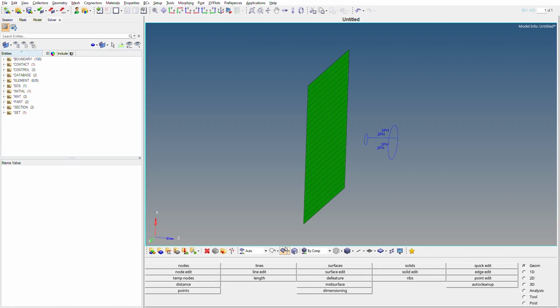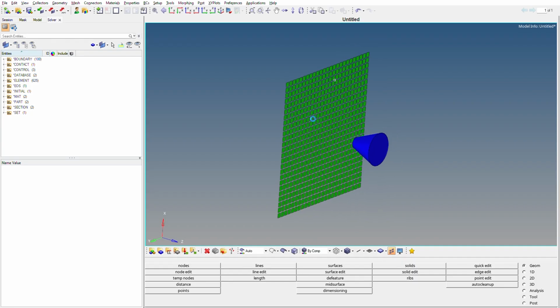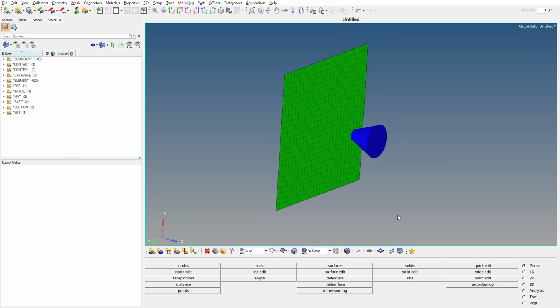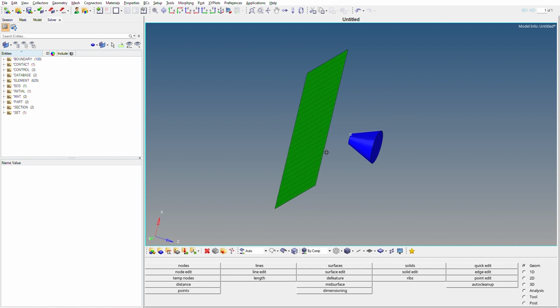So what we'll do in this is we'll create the mesh first, right? As you can see, I have used quad mesh here for the surface. You can see this green color, right? You can just observe. Okay, and then I have used SPH particles for the elements which are coming and colliding with this rigid surface, right? Next, we have created the elements, right?